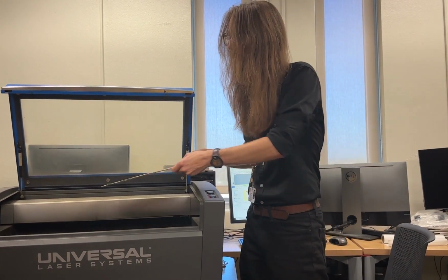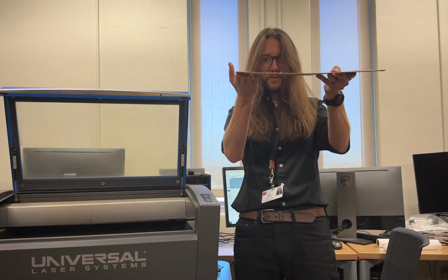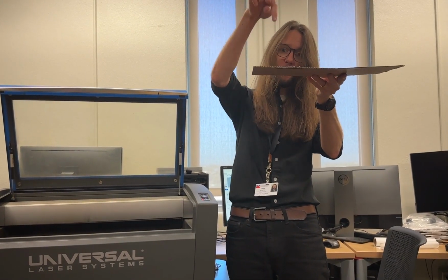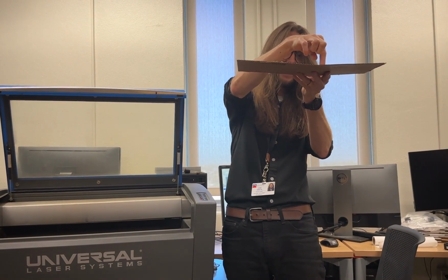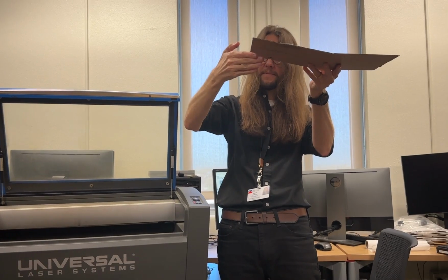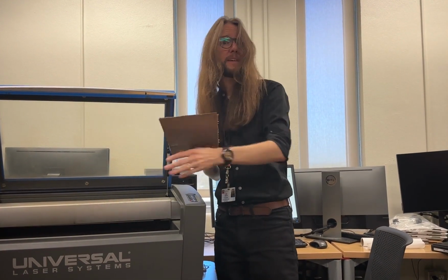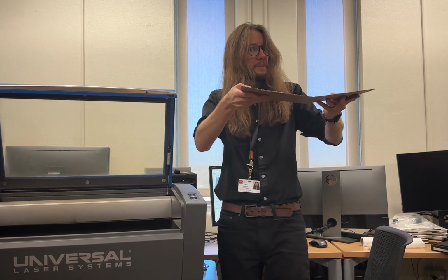So if you notice your material doesn't fit, you need to make it exactly 12 by 24, even just a little bit off, guys. Again, that focal point is going to cut here because it's at a certain depth, where over here it might not because it's off the bed. Relatively, you want extremely flat material. And let's face it, some basswood is bent up a little bit.